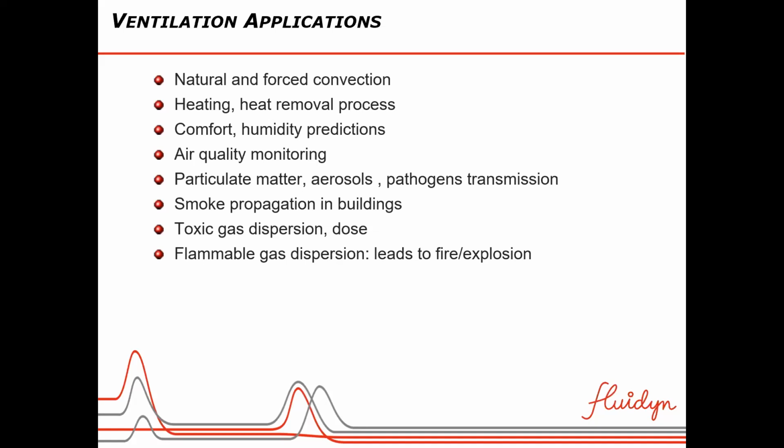In addition, from a particulate matter point of view, aerosol transport we can also do. This is not a Lagrangian particle approach; it is in the fluid solver itself. We have an aerosol model. We solve different passive scalars, and for the interaction with the walls and the settling we have separate models. In addition, we can also simulate pathogen transmission.